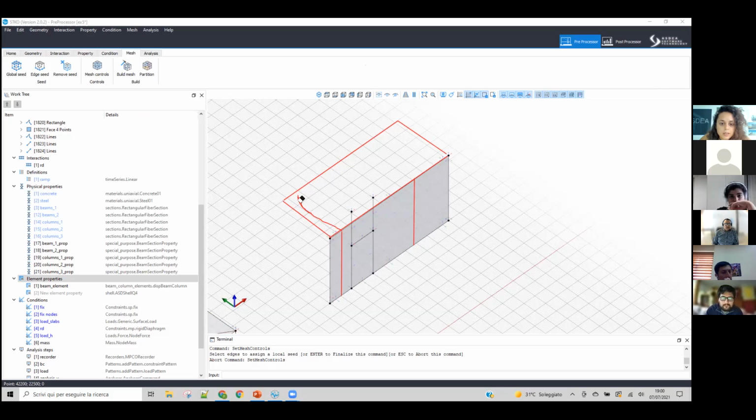Yeah, your mesh is gonna be divided like this, no? Because you will have to imprint these lines on your face before, to be able to have a coherent mesh between the face and the rest of the structure. But you don't assign any property to the line, and you have just like this reticulated shell. You don't even need to define it more here.